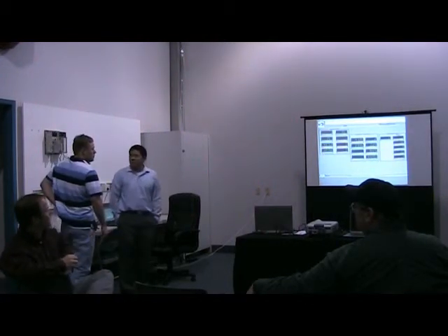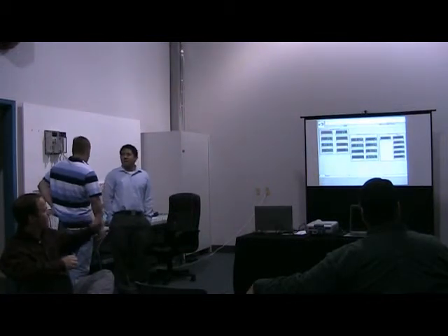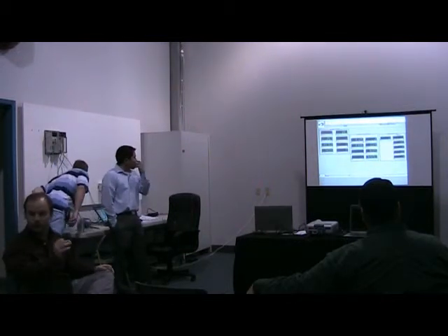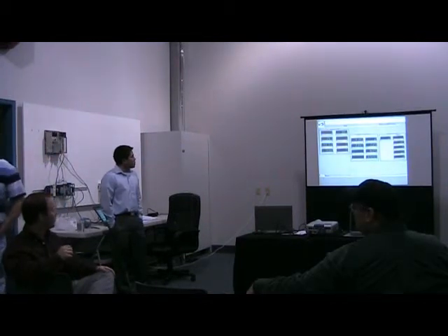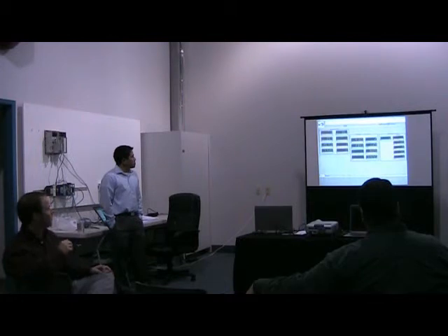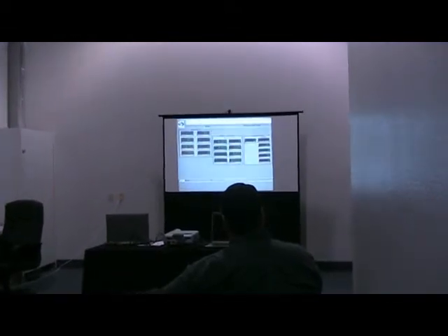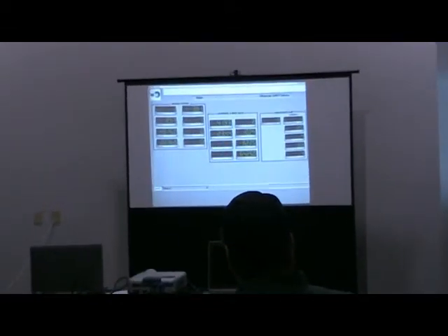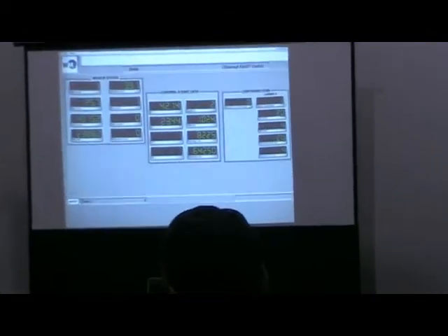So on this example, the instrument is scaled 50 degrees to 150 degrees. I don't know if you put it in there or not, but your 4-20 milliamp signal is 3.91, below 4 milliamps. So your screen would be showing 50 degrees. That's all I was going to show you. The actual real-world process variable is 42 degrees and dropping.